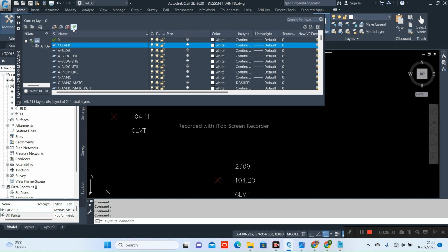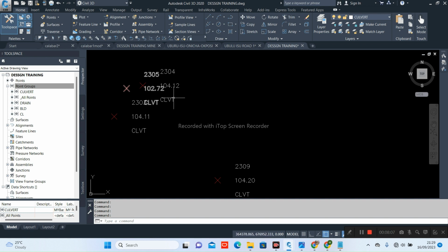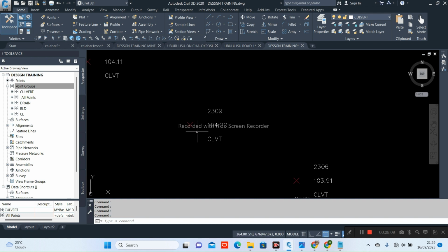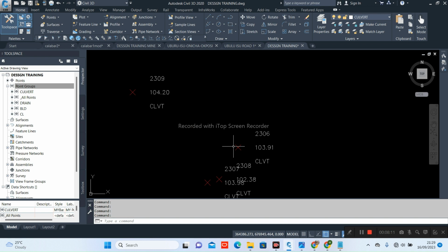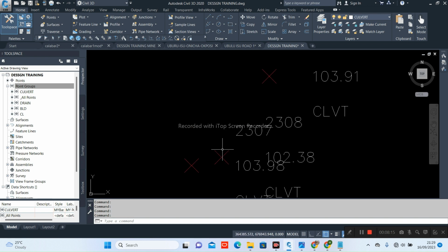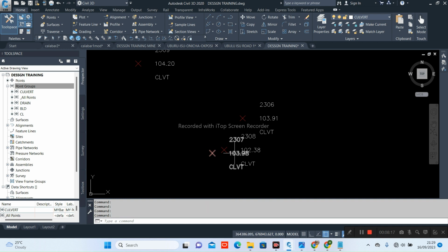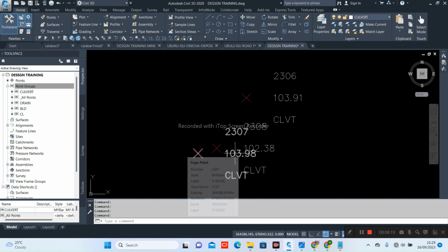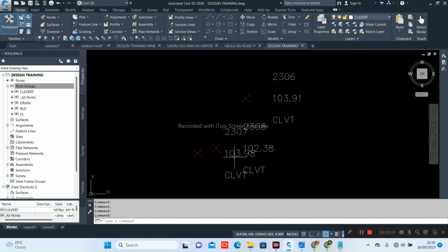So you can set it correct. So you close it. So now this is the center of the culvert. This is the culvert. This is the edge. Mostly what some people do is they pick the invert. The invert means the base of the culvert, that is like the bed of the stream or the river. So you can just say L, you draw your line around it.